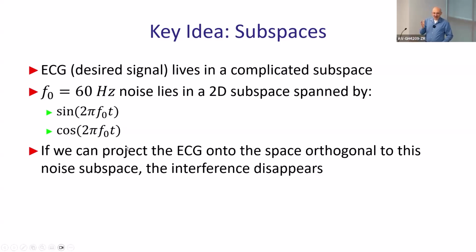Okay, so the idea is, first of all, to project your given noisy signal into the noise space, which means finding the closest noise components that you have in that signal. What is projection? Orthogonal projection. It's perpendicular, which means the closest one, right?